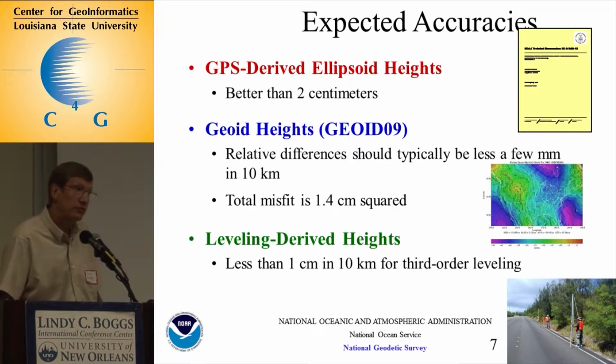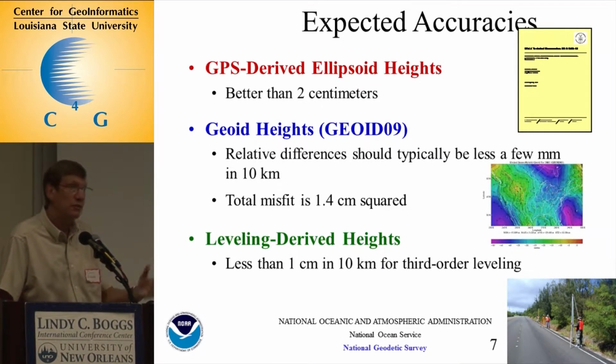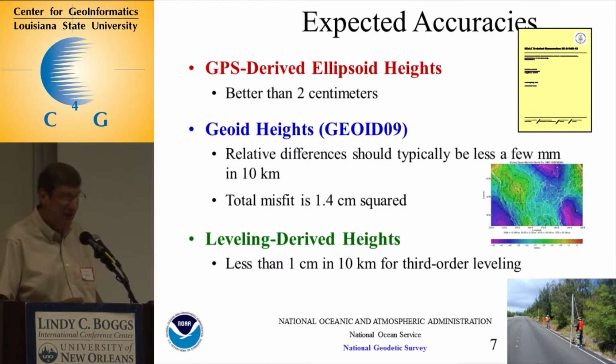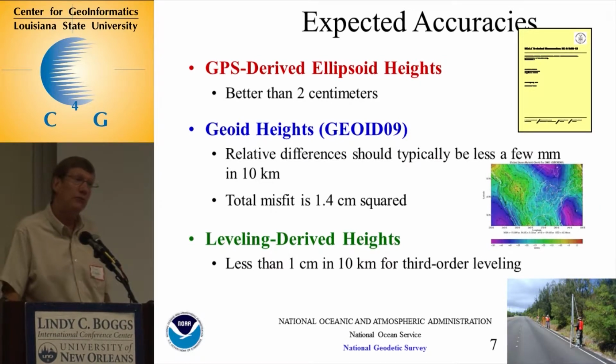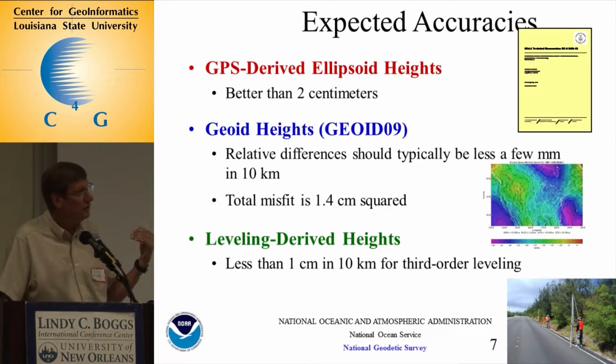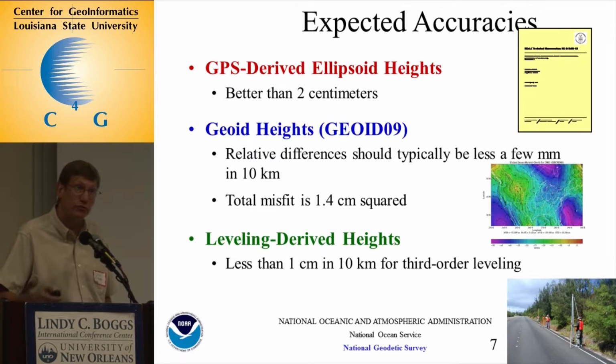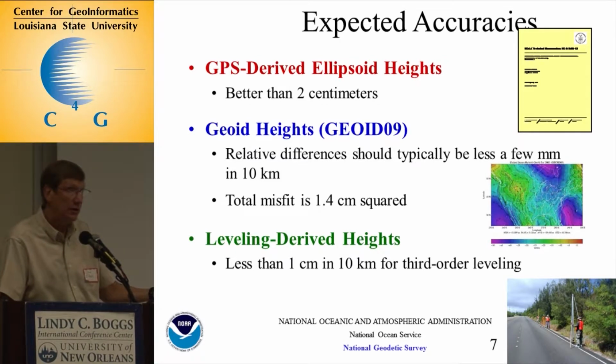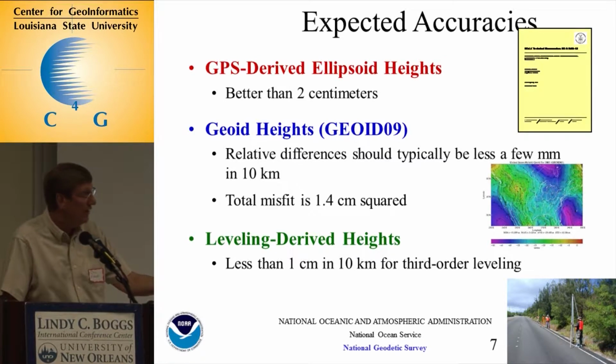The difference in the error in the geoid over the slope is less. And that right there is a key to how you use these procedures and try to get GPS-derived orthometric heights. You're going to see that they don't match up if you try to do it point by point, which could be an issue when you're using OPUS and standing on something and you get a value there.